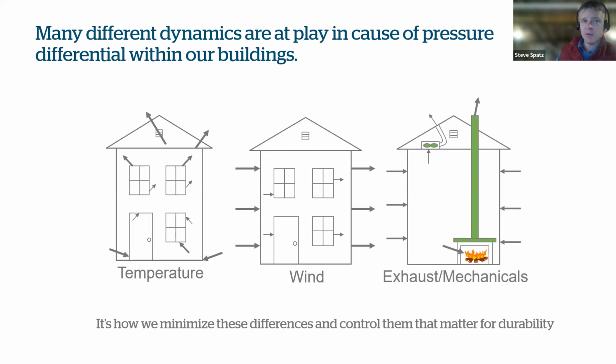What we do have a lot of buildings experiencing in our built environment, especially in the Northeast, is buildings that were built before there were central heating and cooling systems put into them. Those buildings now have furnaces and boilers in them and chimneys and ways of needing to exhaust combustion gases from equipment. And pressure dynamics within buildings can change the ability of that draft to work the way that it should, just naturally. And then also mechanically, you can throw things off balance by changing pressure differentials, by putting in exhaust fans where there wasn't before, and atmospherically vented equipment or fireplaces that are relying on a certain amount of air from within the building for that draft and those combustion gases to get outside. So this is a big factor when it comes to retrofit work of existing buildings, really understanding the dynamics at play for the potential of depressurization for existing mechanical equipment.